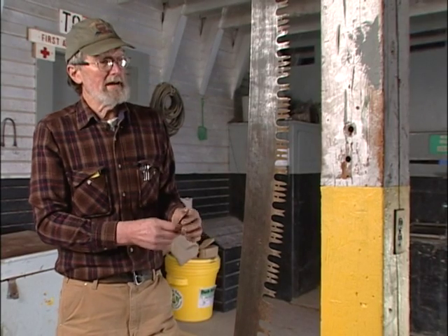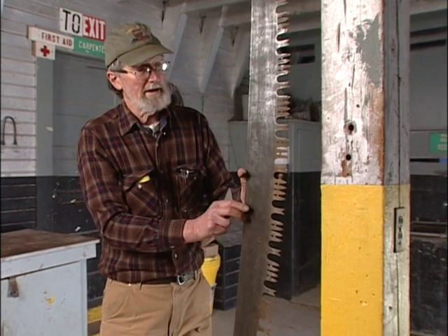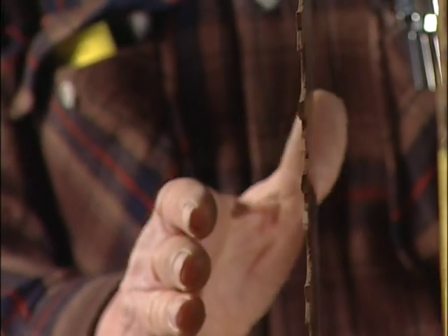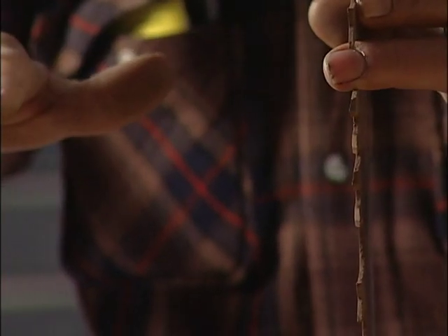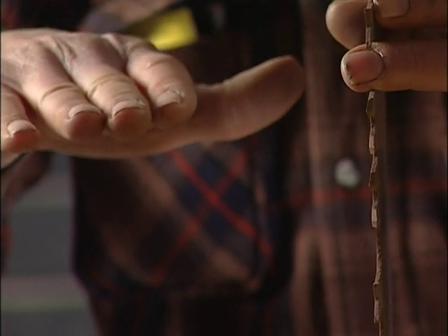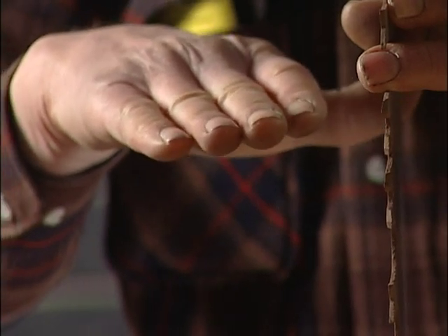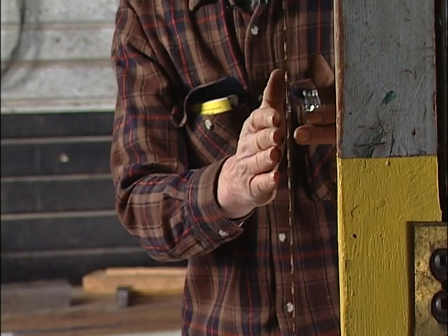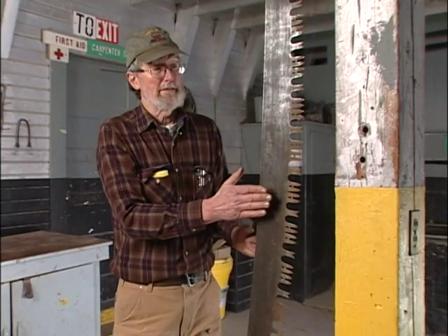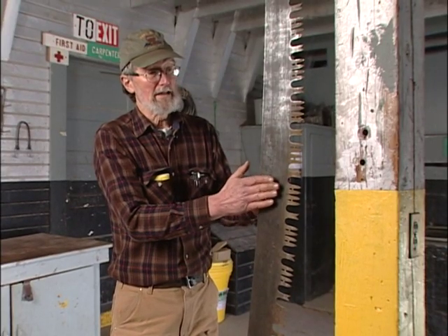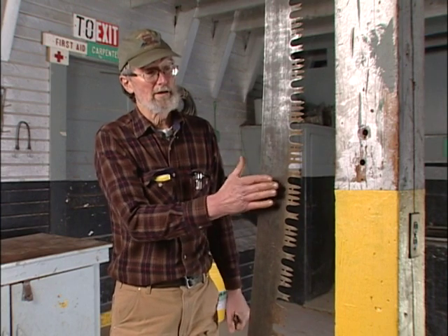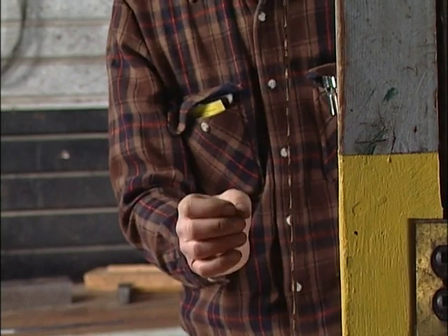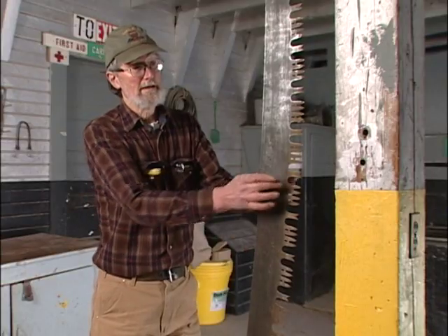If I have a tooth that has a lot too much set in it, it's very difficult to take that set out with the normal set adjustment procedures of using a small hammer and a small anvil. What I'll actually do is, using the large straightening hammer and the large anvil, there's a lot less chance of breaking a tooth. It's a much easier process to take a lot of set out of a tooth than with a small hammer and an anvil.